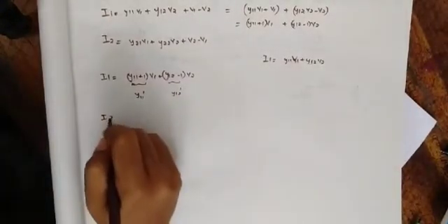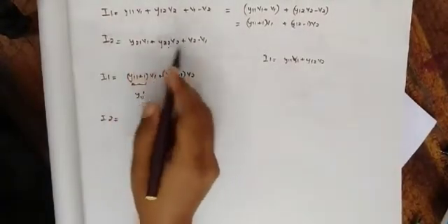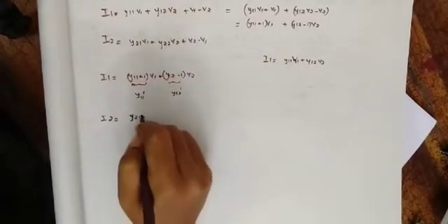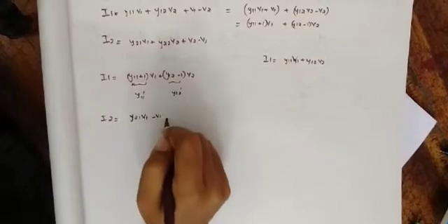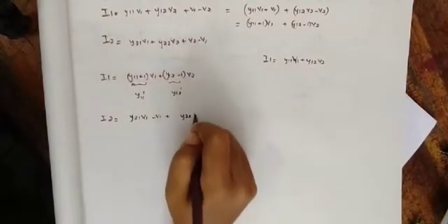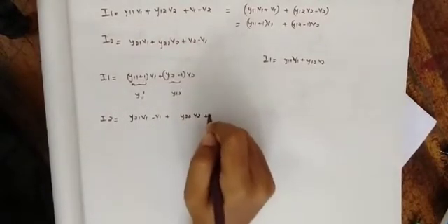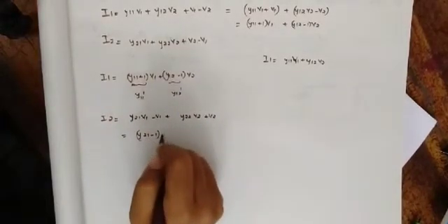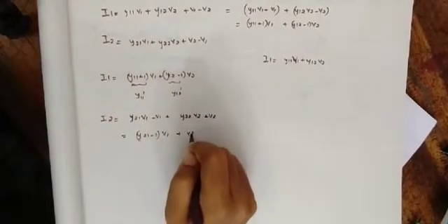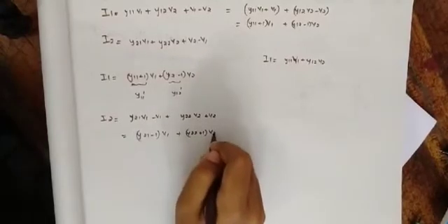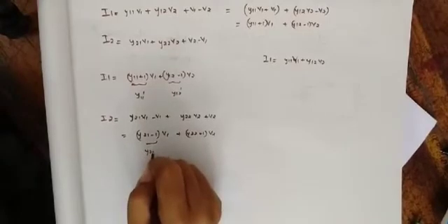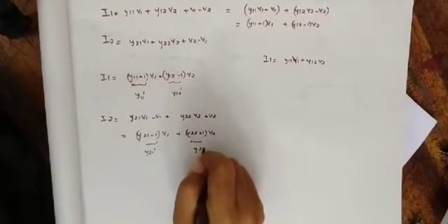And taking I2, taking the V1 terms only, we will get Y21 V1 minus V1 plus Y22 V2 plus V2. So we will get Y21 minus 1 into V1 plus Y22 plus 1 into V2. So this will be our new Y21 dash, and this is our Y22 dash.